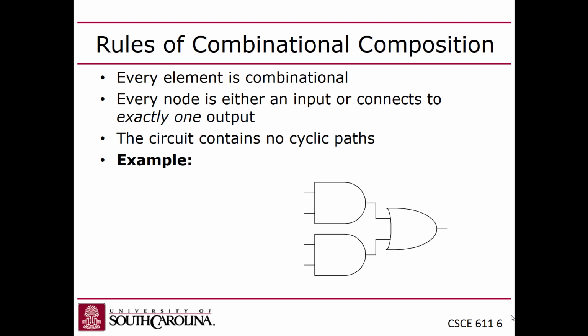If you do that, you could inadvertently create sequential logic by having these cycles, right? The problem is that making sequential logic elements like flip-flops is actually pretty tricky, because it's hard to make circuits like that that are stable. And so in general, if you have any cycles inside your logic gates, it means you messed up. There's a bug. It's usually unintentional, right? You guys with me? Okay.